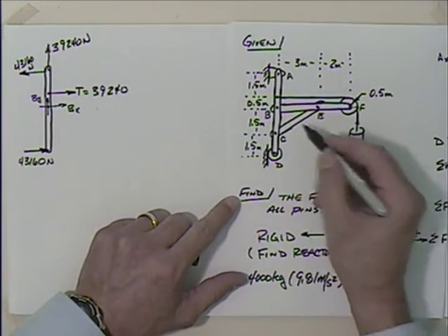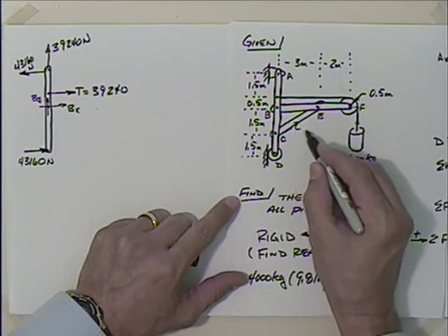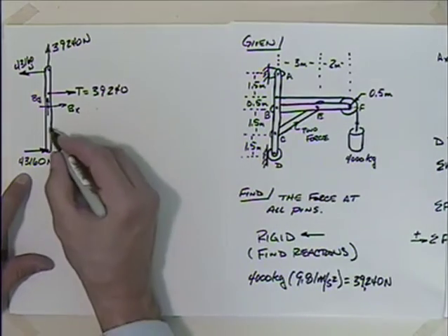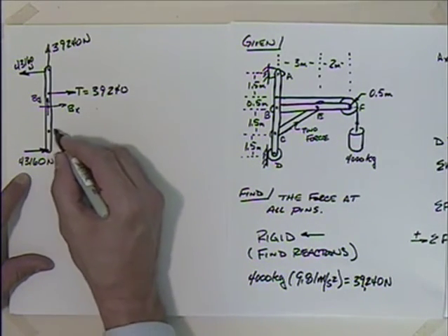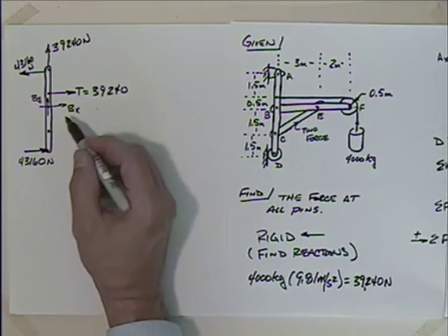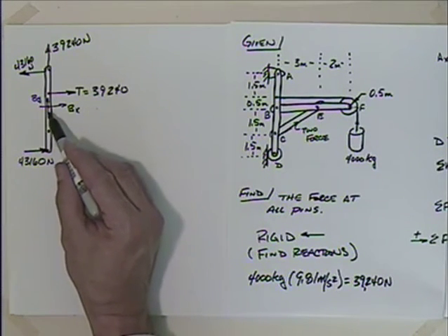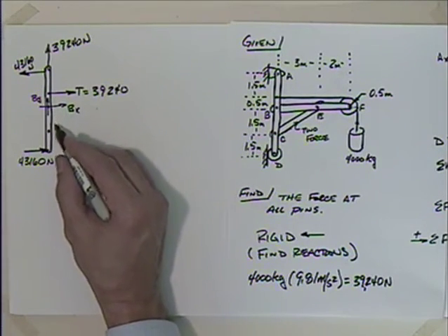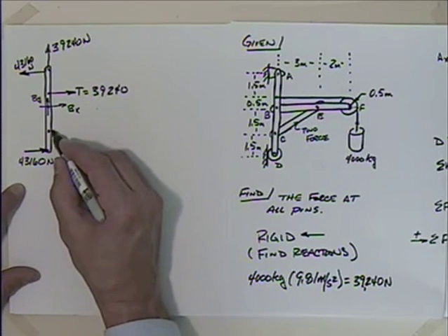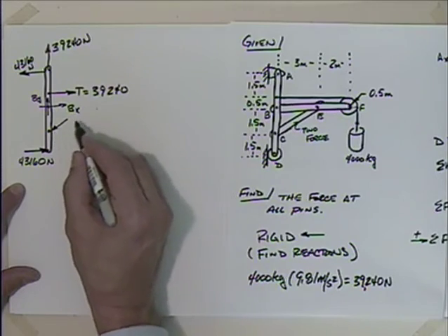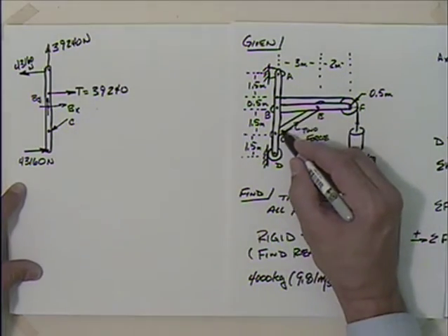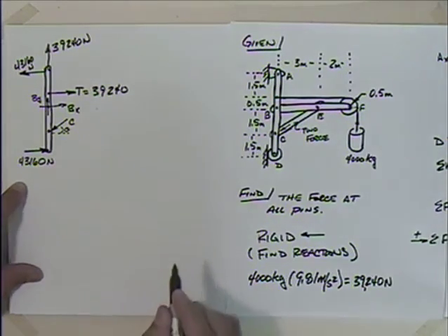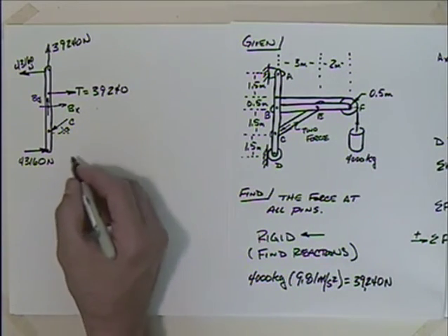And then the last thing is, we mentioned this was a two-force member, right? A two-force member. So I could come down here to C, and I could talk about C having a CX and a CY, but then I introduce two more unknowns. Whereas if I can deal with C a little differently, I'll only have one more unknown and three total. So let's use C as that two-force member. So I'm going to say that this is C. That's acting along this axis here. And we'll talk about this angle theta.